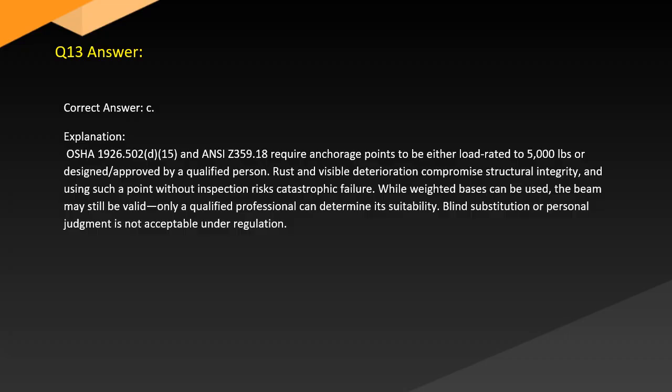Answer. Correct answer: C. Explanation: OSHA 1926.502(d)(15) and ANSI Z359.18 require anchorage points to be either load rated to 5,000 pounds or designed and approved by a qualified person. Rust and visible deterioration compromise structural integrity, and using such a point without inspection risks catastrophic failure.